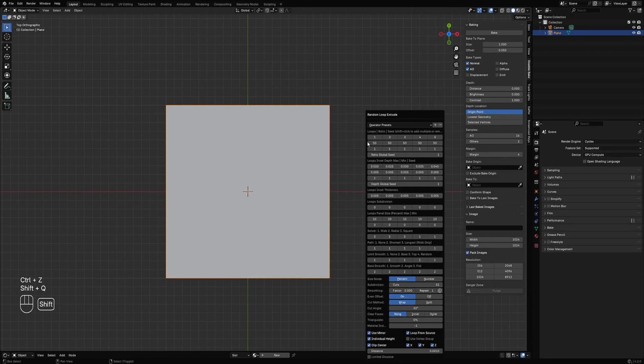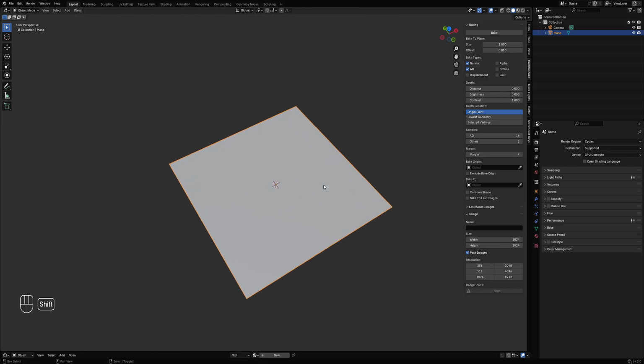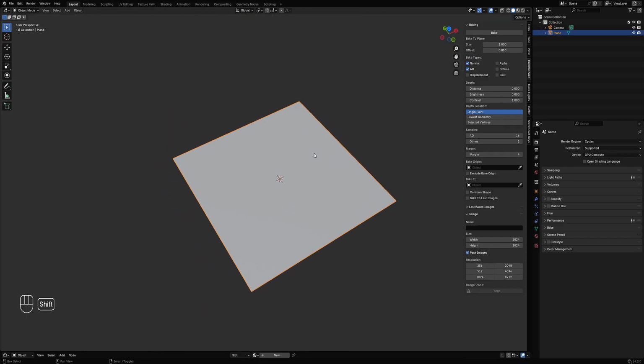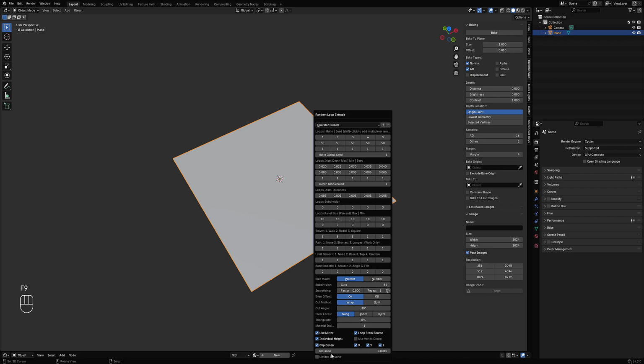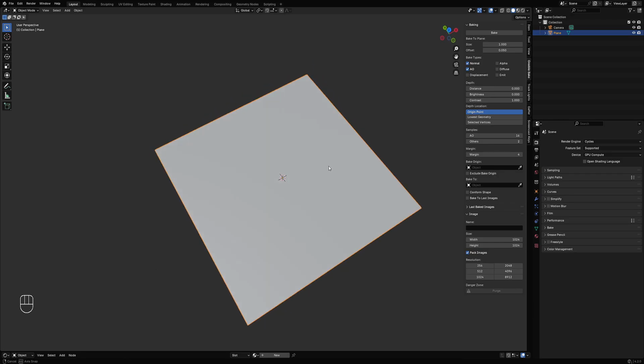But if you haven't touched the viewport, you can see that it's changing correctly. So if you don't want to have this bug, just use 4.1. But if you're using 4.2, then you can go to the preferences of the RandomFlow add-on and use the confirm menu instead. There will be an OK button here, and then you can use the redo panel here, and the bug will be mitigated, but it won't be as prevalent or as persistent.